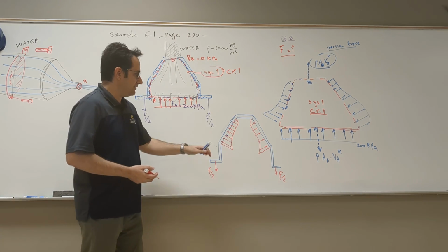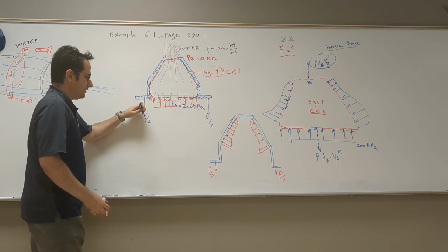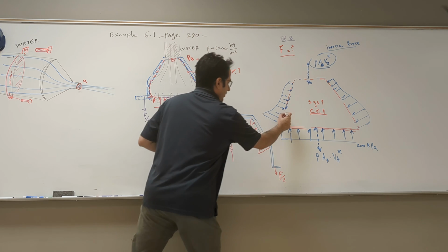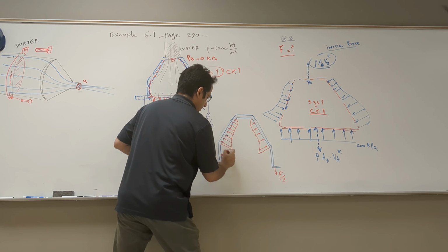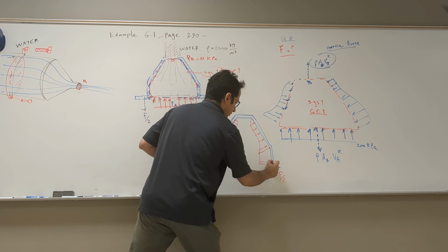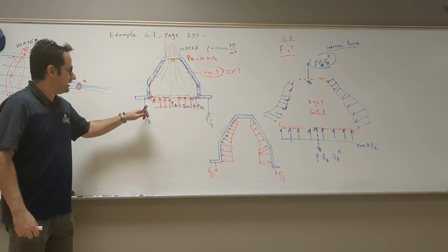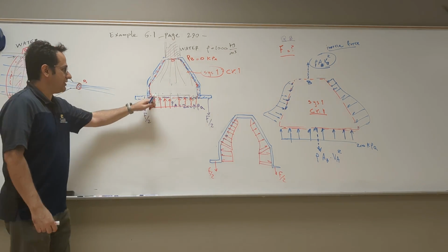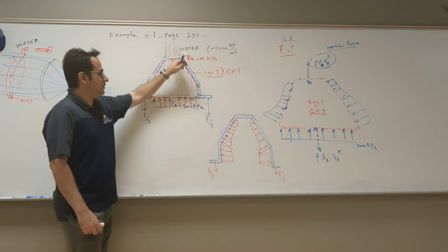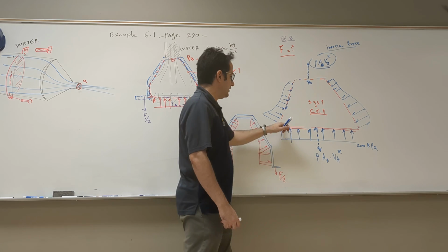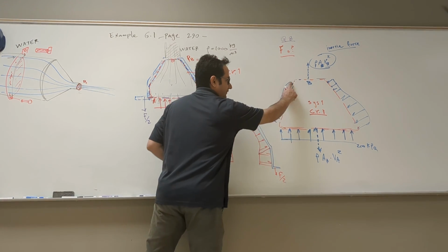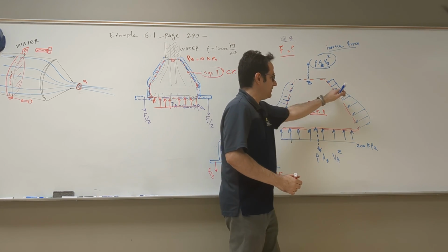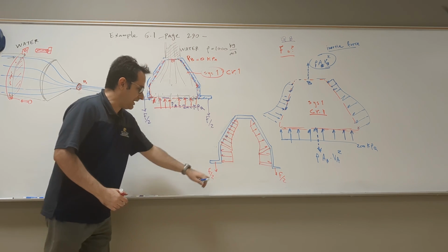The only way the nozzle is interacting is through, and also there is another load here. You see, this part, there is a load here. I just draw it like that. So the only way the nozzle gets the forces is through interacting through this space with the fluid. You see that? The nozzle does not feel the pressure here or the pressure here, the inertial load. It only sees the surface loads on the fluid. So if you get the result of this, the result of this should balance with F/2.